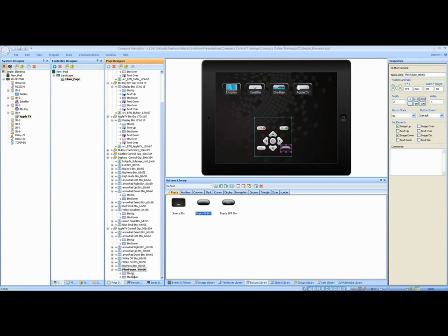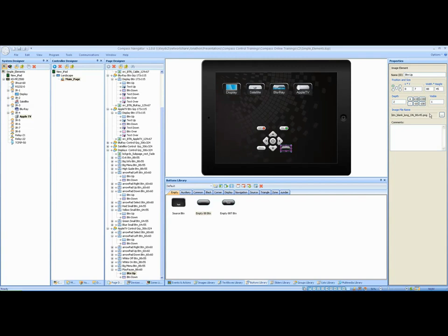And we know that the appearance of the button really is just an actual PNG image. So what we are going to do is invert these images. And you could do it one of two ways. I've showed you one already, where we've opened up the Key Digital directory, gone into the resources folder, and pulled the image of the silver button for the up state and used the image of the black button in the down state, for example, is what we would do here.